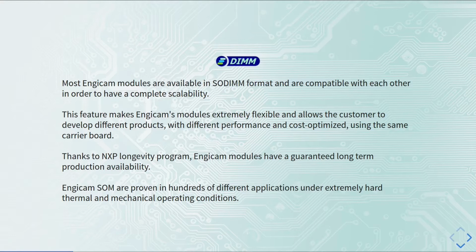So if you are creating a system for a specific application with an EDIM system on module and you realize that you do not have enough computational power, you can just unplug the module you are using, plug in another module with a different processor and higher computational power, and then keep on developing your system. So there is compatibility and also complete scalability.